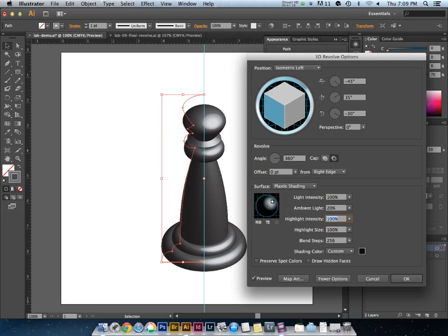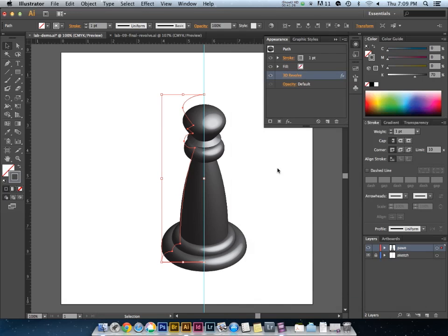But there's also ambient light coming in from the window there, from your monitors, and that's basically what the ambient light is. And I've changed my ambient light to 20, and now you can see I'm getting a much sharper rendering with that object, and because I've got 256 blend colors, it looks pretty darn smooth.